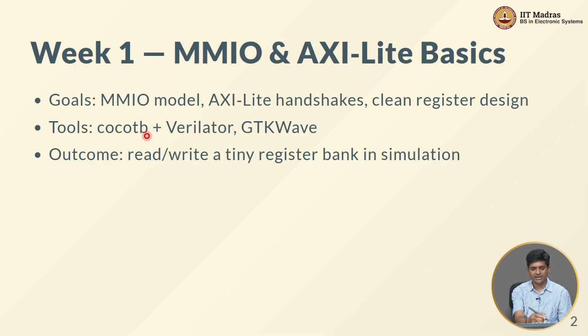So, unlike the iVerilog simulator that we were discussing earlier, we will be using another simulator called Verilator. By the way, iVerilog also could be used, but Verilator is a bit more powerful for larger designs, as we will see. So, what we will be doing is writing Verilog code and a Python test bench, combining the two using Cocotb, and we will see how it can be used to run, once again, self-checking test benches and also at the same time to view the waveforms that result from the simulations that we are performing.